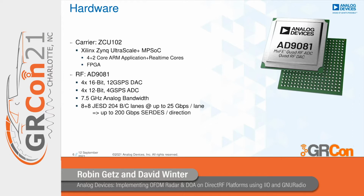To get the data off of the chip, there are 8 JESD lanes available, which allow you to transmit up to 200 gigabit per second to and from the device. But in my application, I'm only using around 40 gigabit per second of bandwidth.